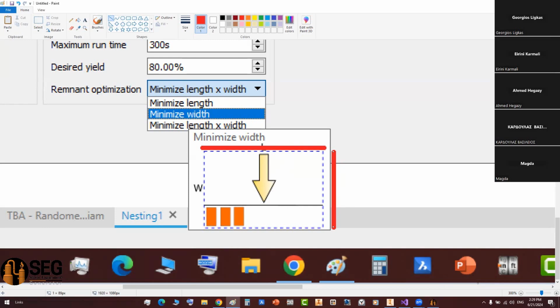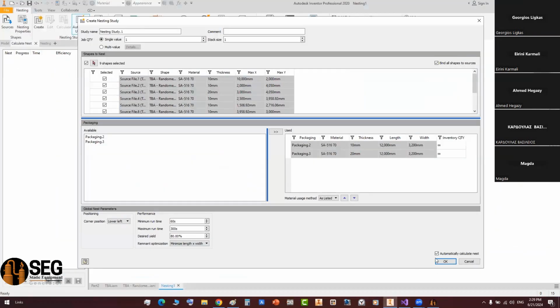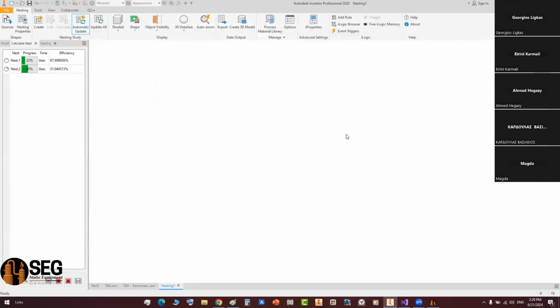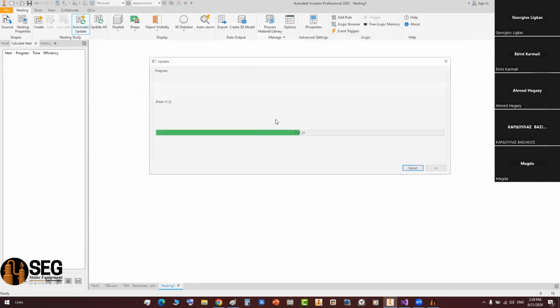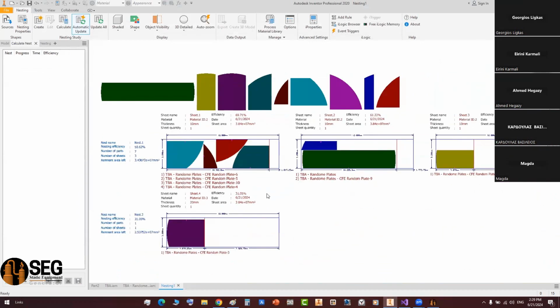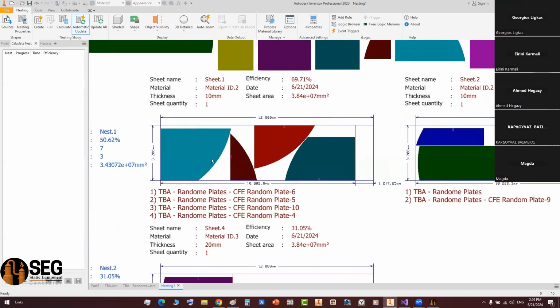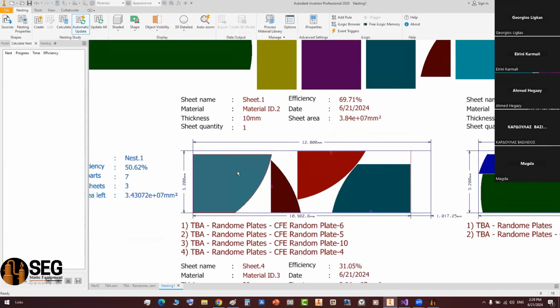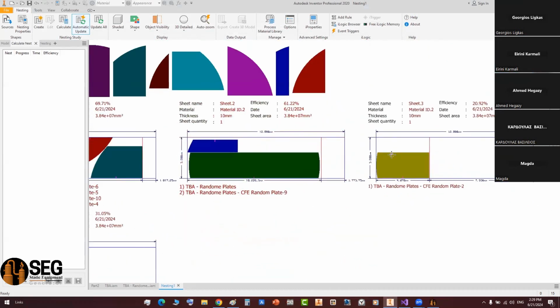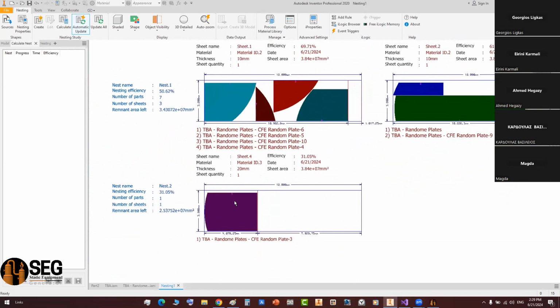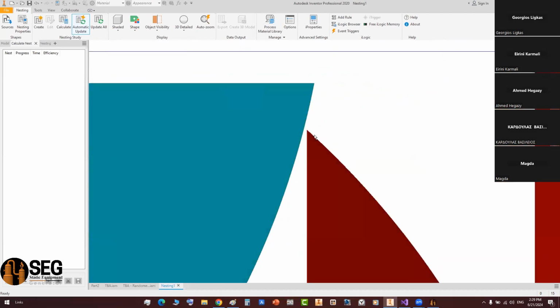Now, so by doing that, let's select the minimize lens and click on OK. And now the software of the nesting tool will make the arrangement of blades. So here you will get that arrangement for the blades based on the blade length that you give it to the nesting tool, the blade width and the frame offset and the item separation.